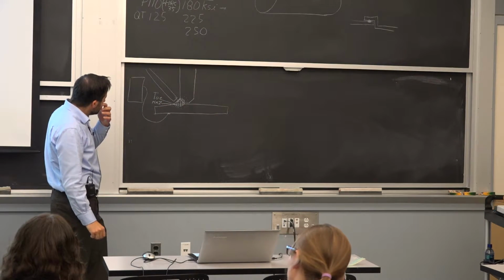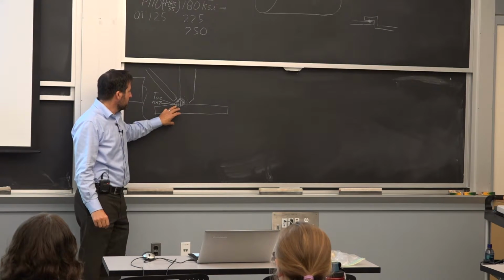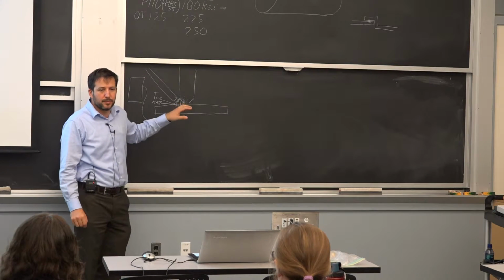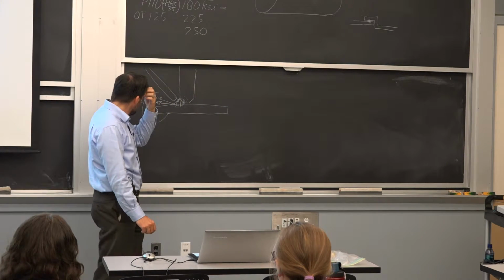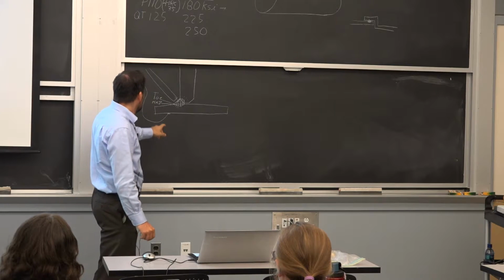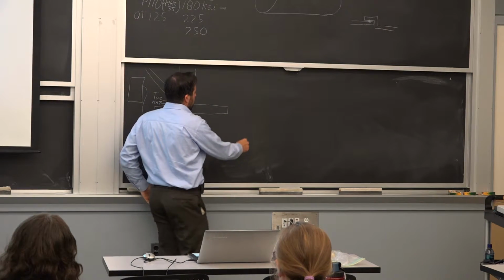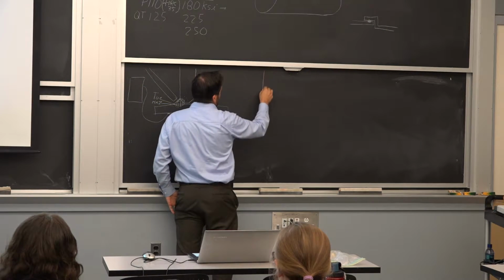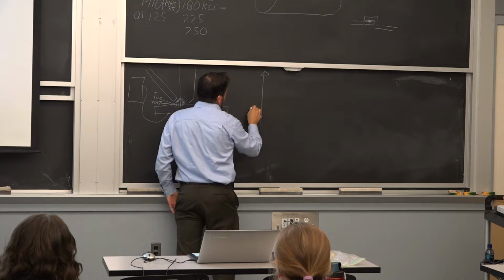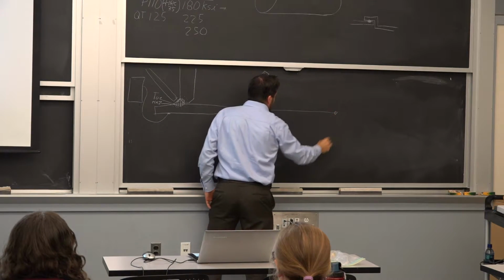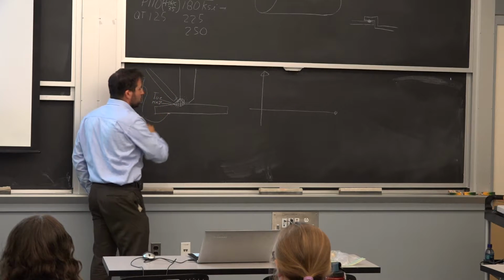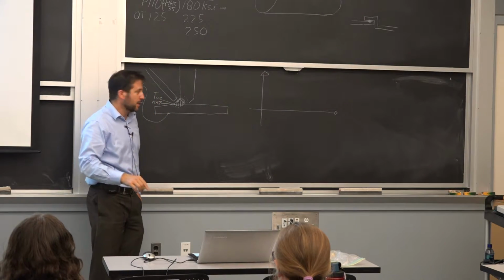So depending on the material you have, and I can be general here and do both aluminum and steel. If we're talking about aluminum, from what we've learned Friday, when we heat it up enough, we go back to solution and quench it, it's very soft.